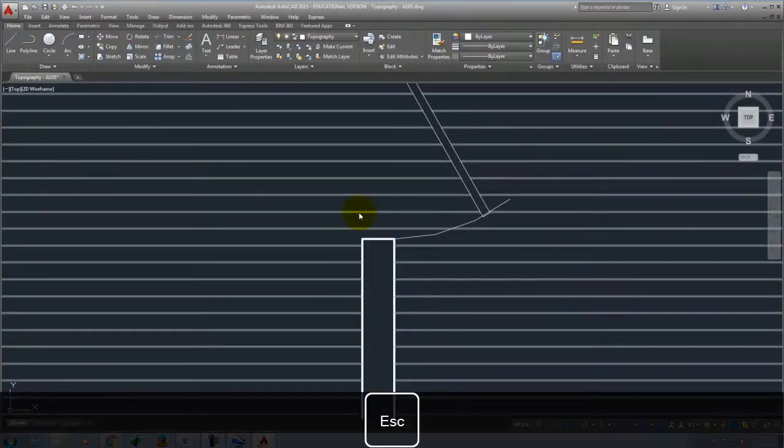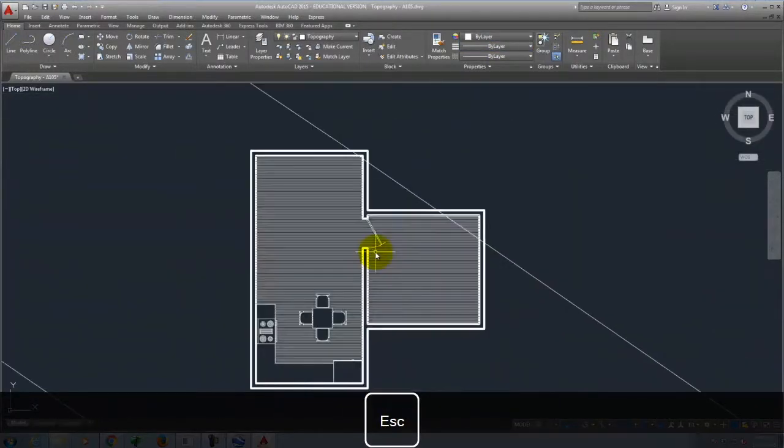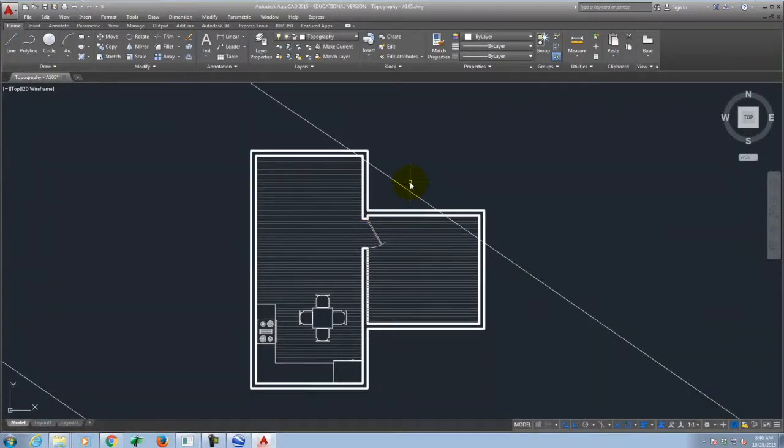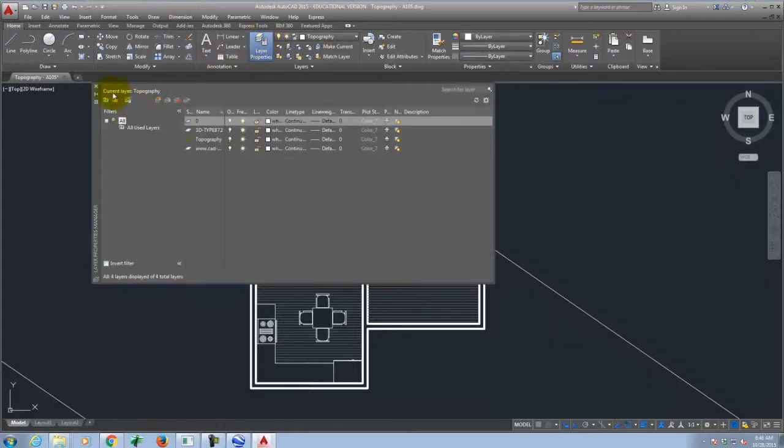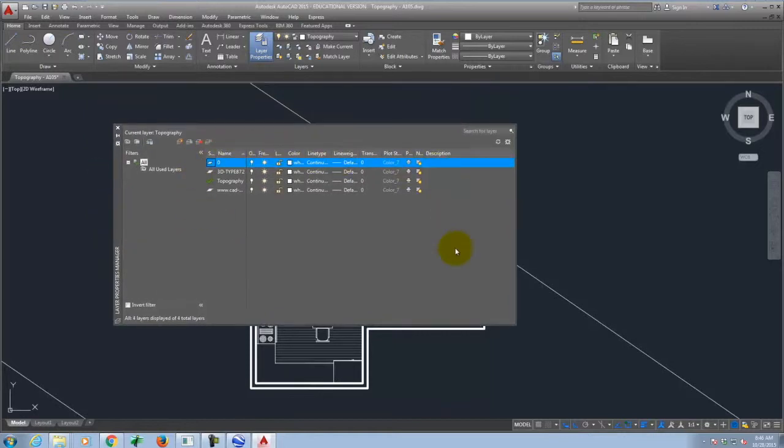Okay. So you certainly can go through and apply line weights to individual lines, but sometimes it is better to apply things to a layer, and it's certainly easier to apply them to a layer. So let's talk about the layer properties for a second. I'm on the home ribbon, and in the center here, I have a section called Layers. Inside the Layers section, I have a big button for Layer Properties, and I also have a drop-down menu that shows the various layers that I have in use. I'm going to click on the Layer Properties button, and I get the Layer Properties Manager popping up.